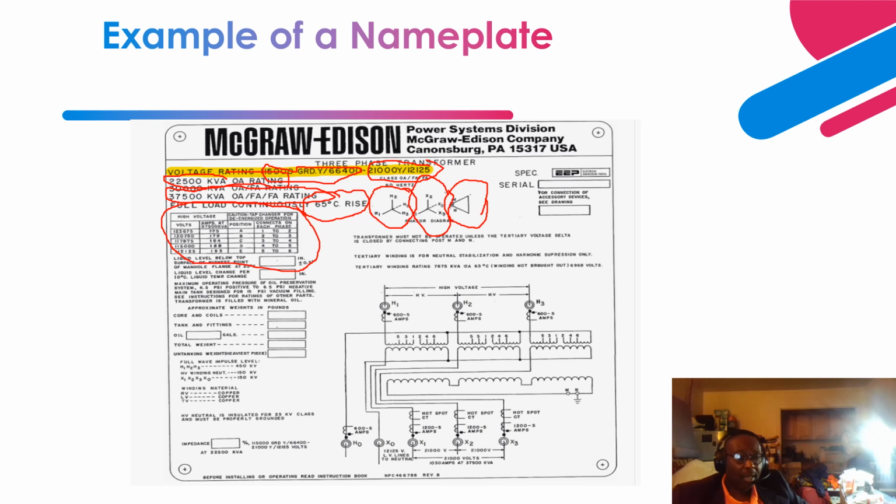So this tells you all the voltages that can be achieved based on that voltage variation utilizing the de-energized tap changer or offload tap changer, right? And it tells you all the currents that can be achieved. Then the different tap positions from tap A, B, C, D, E, shown over here. And this is all the currents and all the voltages due to that voltage variation.